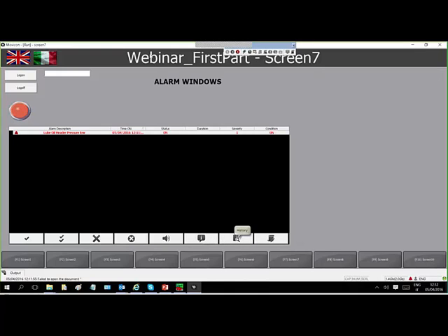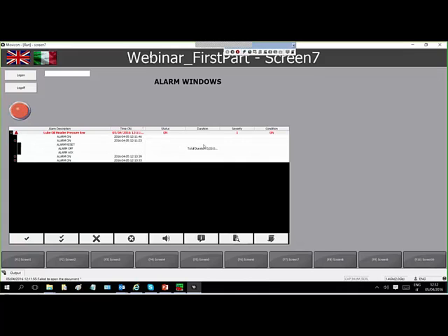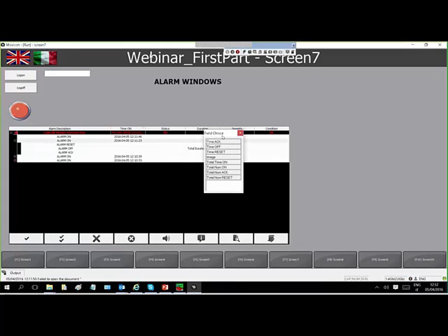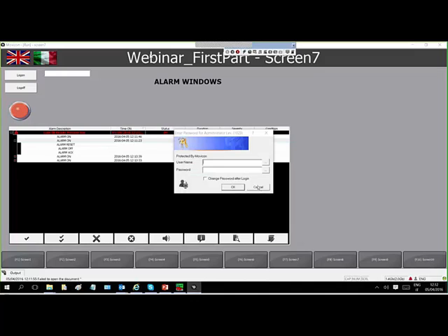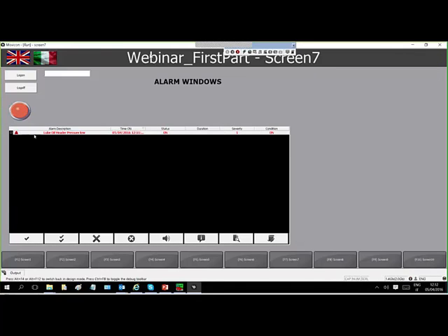You can see the history of the alarm. Very important point. If I click on my alarm line, clicking the history button, it will open here to show what was the history of this alarm. It was present many times, and I can monitor what was the duration of the alarm. I will show this also later. And at the end you can add a comment on your alarm.